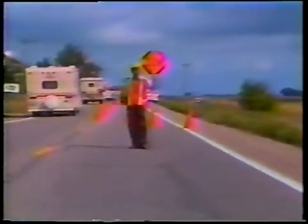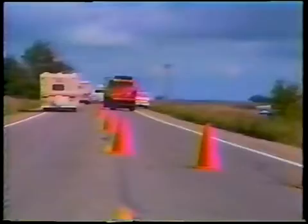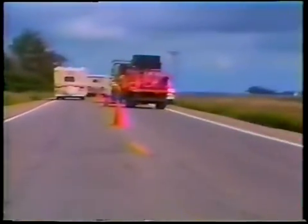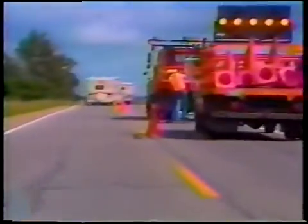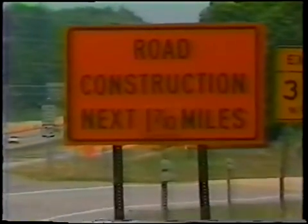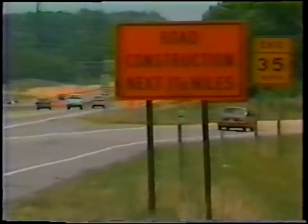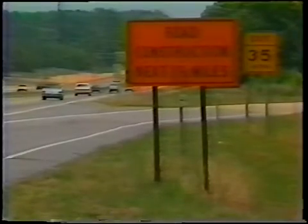Avoid gaps in the traffic control at work zones that may falsely indicate to drivers that they've passed the work area. For example, if the work includes intermittent activity through a 1-mile section, drivers should be reminded periodically that they are still in the work zone. The primary purpose of the guide sign, Road Construction Next Miles, is to inform the driver of the length of the work area. It should not be erected until work begins.